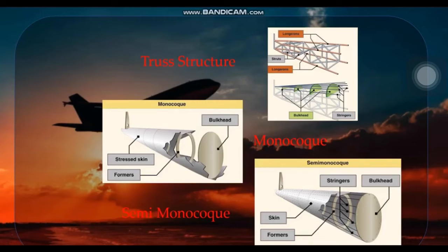Monocoque is not highly tolerant of deformation of the surface. For example, an aluminum beverage can supports considerable forces at the ends of the can, but if the side of the can is deformed slightly while supporting a load, it collapses easily.